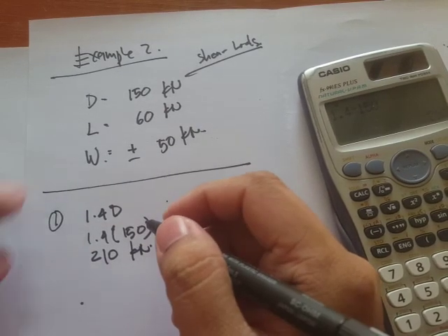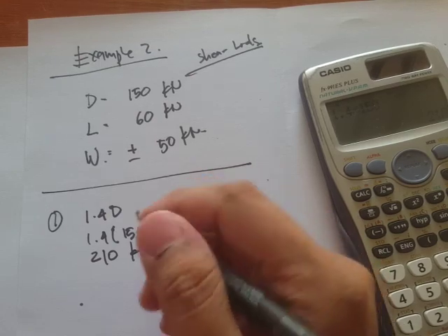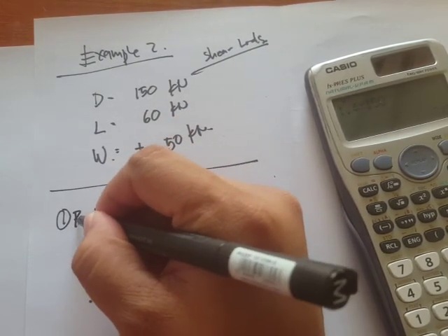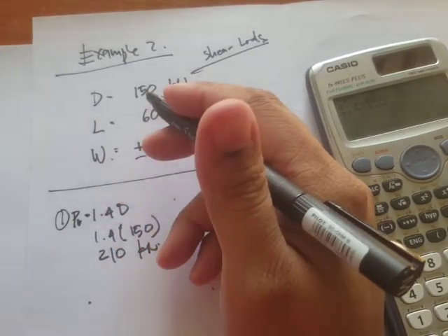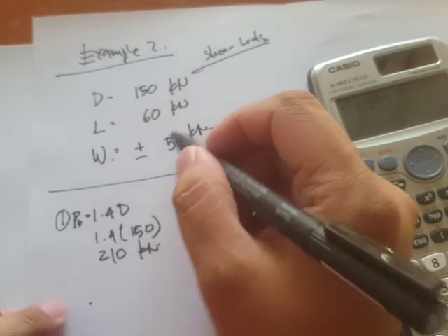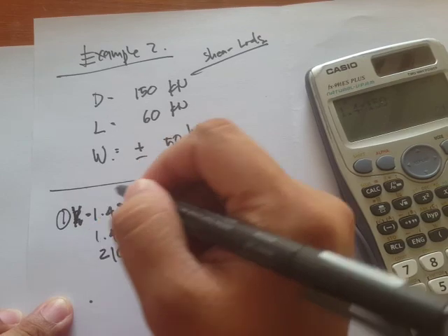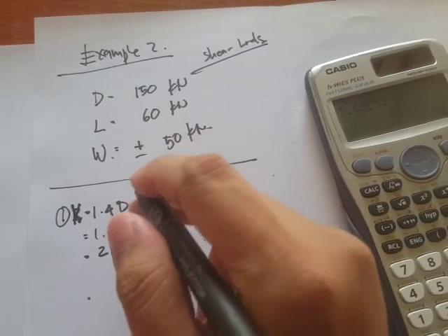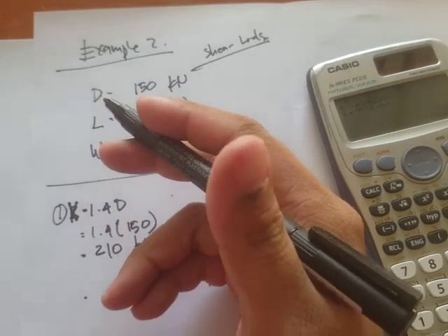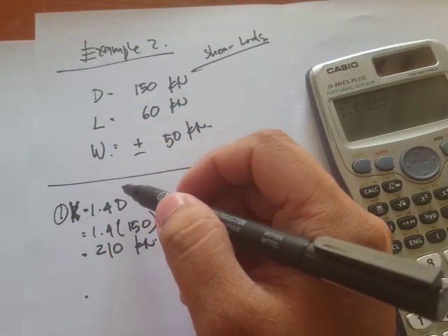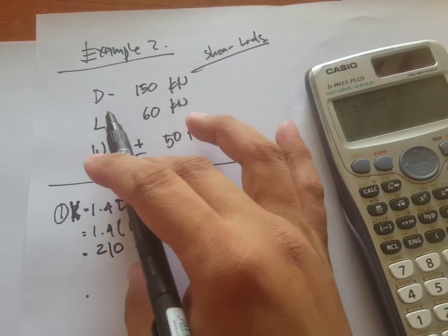Okay, so I guess we should write a symbol here. Let's say a P sub U. Or no, this is shear. Then this should be V. Sorry. So V sub U, meaning ultimate shear or factored shear. You can write it that way. Factored shear load. So we're still on the load sides.